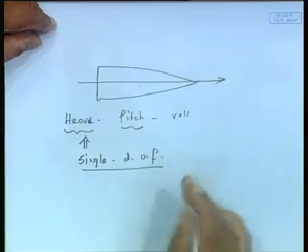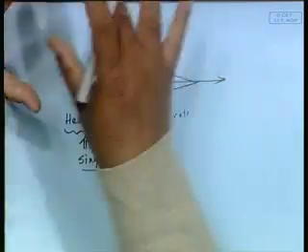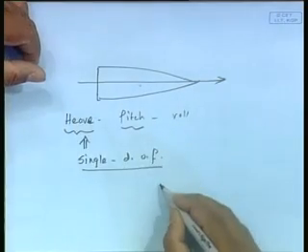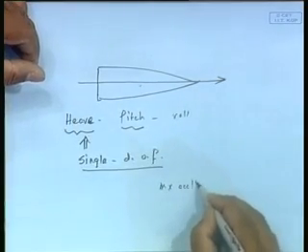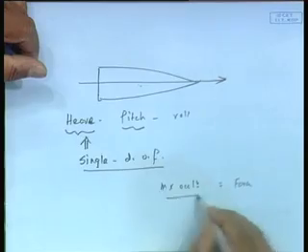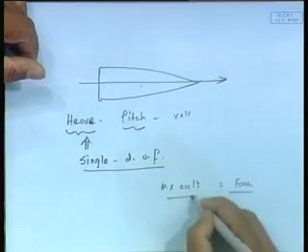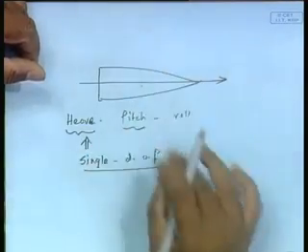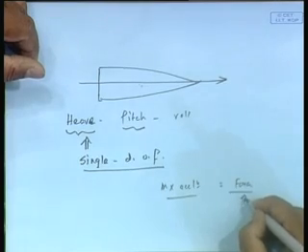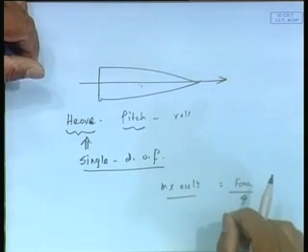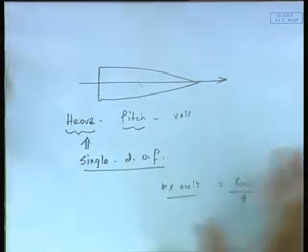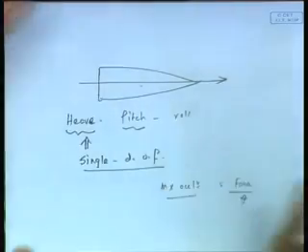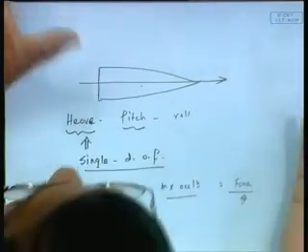Okay. So this is where the concept of single degree of freedom equation of motion comes in. Any equation of motion you are going to write is mass into acceleration equal to force. What we are saying here is that if I were to accelerate the body in heave, for example, it is not going to get a force because of the consequent pitch or trim. Everything is only heave. If it heaves, it only heaves, it does not trim. If it trims, it only trims.